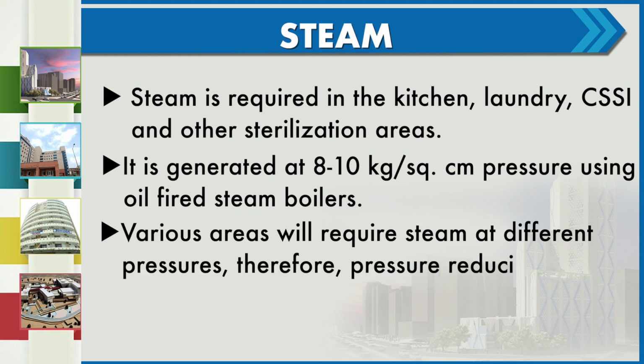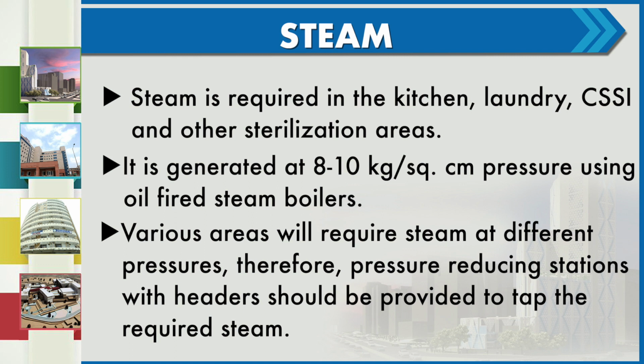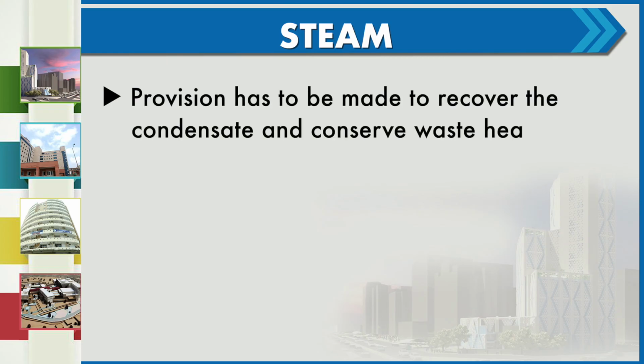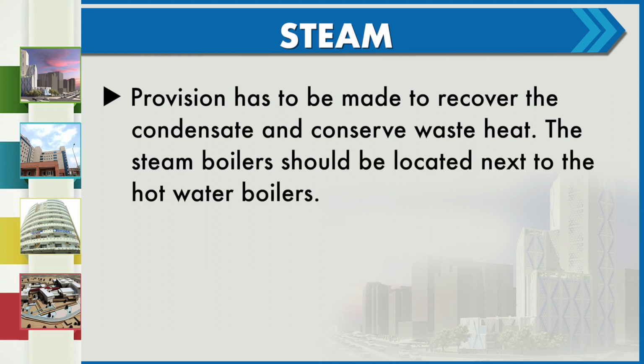There are various areas which require steam at different pressures. Therefore, it is very important that pressure reducing stations with headers should be provided to tap the required steam. We should also take care that the pressure is recovered by condensation and conserved waste heat.